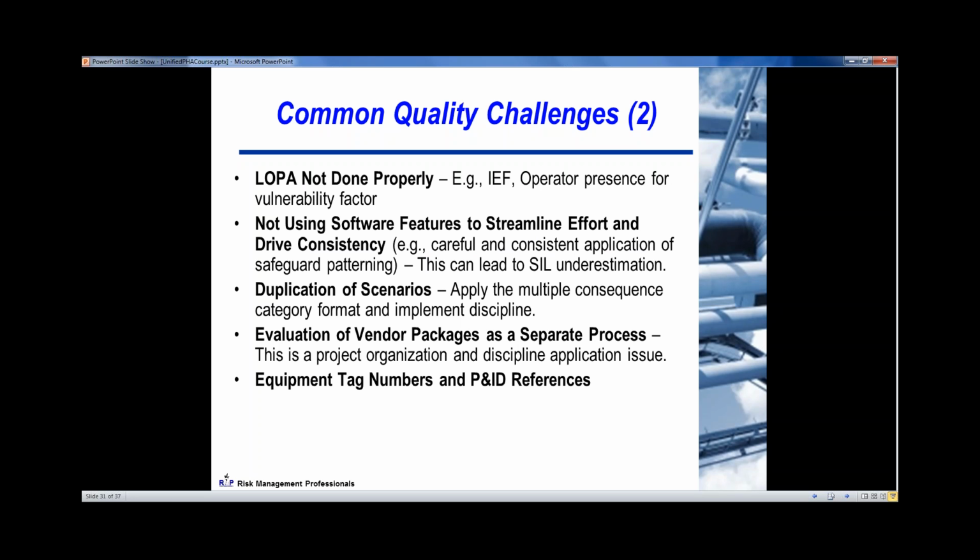Another common thing is if you've got an alarm and you've got a manned facility, typically the alarm condition is at the beginning of the upset. Operators will go out to the equipment to identify if it's a nuisance alarm or if it's actually a real event going on.